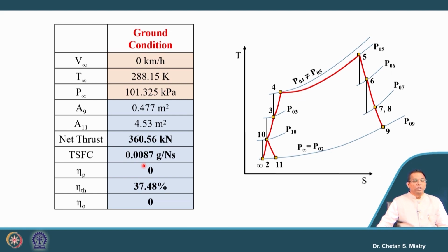So, here we are stopping with all the calculations we have done. We will try to discuss the effect of different cycle parameters on the performance of our engine, or say performance parameters. That will give us an idea of how the numbers for the cycle analysis, such as pressure ratio and temperature, all those parameters, have been selected for the design calculation and for the optimization.